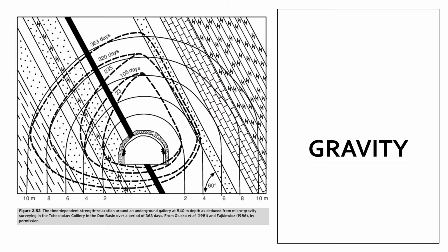Now, if you remove a portion of rock when you make a tunnel, the rock wants to squeeze out into the tunnel. They want to exit, they want to relax a little bit. So when you have a void or a tunnel here, parts of the surrounding rock will undergo fracturing.